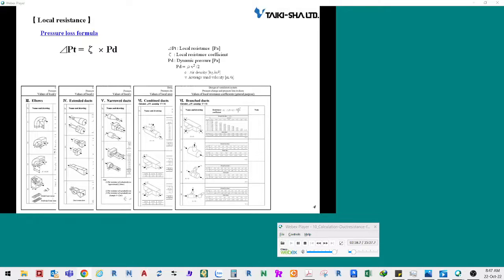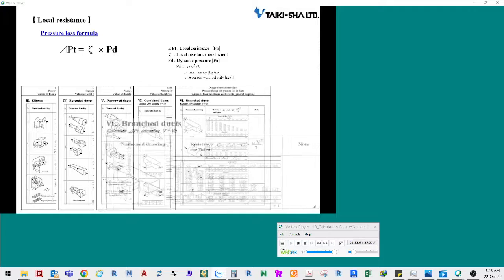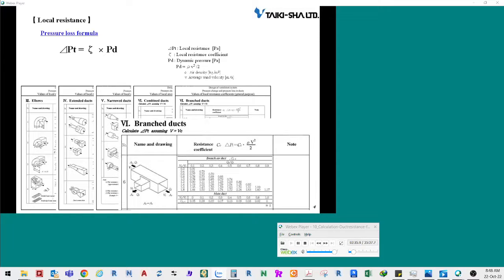If you cannot find the required coefficient, adopt it from various literature or manufacturer's data. In addition, the conditions to be followed for resistance calculation are specified in such engineering materials. Be sure to calculate based on those conditions. In particular, note that the wind velocity changes at a branched or combined point when you use such conditions.